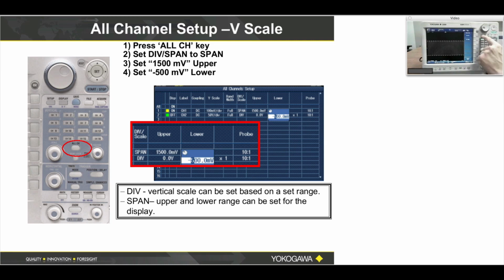Press Setup. At my fingertip, a hard button here called Setup. Press Setup. Go to soft menu button number 7, which is Setup Data Store Recall. And I believe that it's very intuitive here. You'll hit Store Exec. If I hit it while I'm still running, I have not hit stop, it may have an error code.